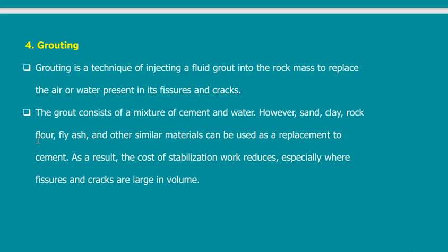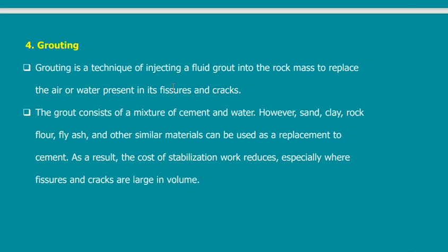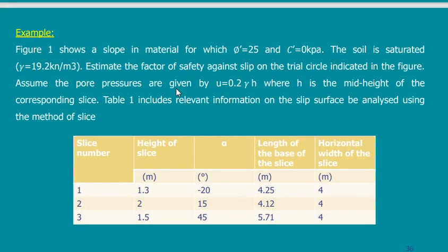But it is very good only if it is applied very well. But if you just pour the concrete or the grout, and you are not sure that it covered all the places, maybe it went to one place and it did not go to the other, then you will not guarantee the accuracy of this grouting method. So if you can do it with accuracy, it is good, but if you cannot, then it is better not to use grouting.